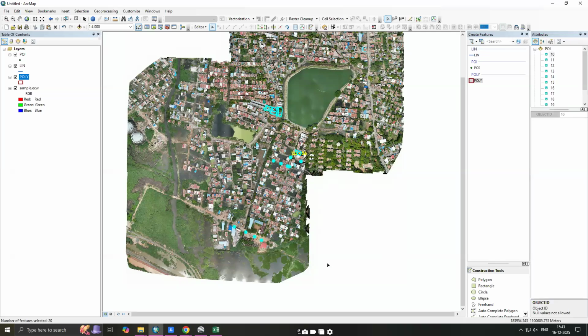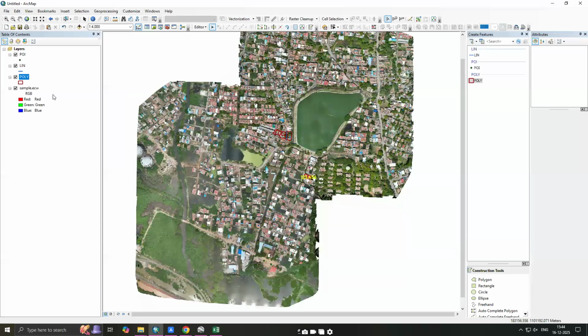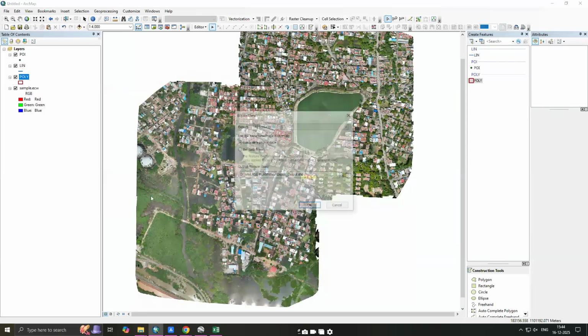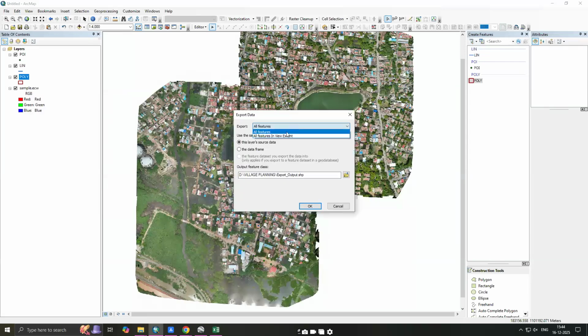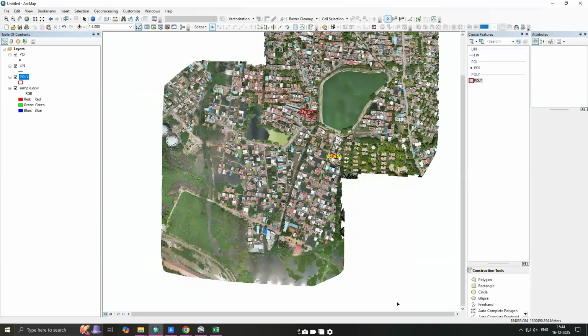For some places, they'll ask for this also. So based on what they want is the number of reports, and mostly this is not delivered as per our database. We just go here. There is one thing called data. You just export data, and here all features should be there, and we'll export it into a shape file. So any data taken from this will be exported into a shape file and delivered. No one will be delivering the database directly.